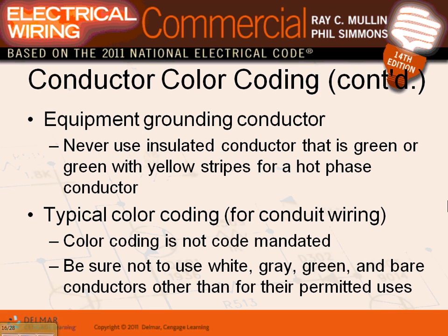We talked about green, or green with the yellow stripes, for hot. You cannot use green. If I have this green conductor, can I identify it as black and use it as a hot? No, you can't use a green.